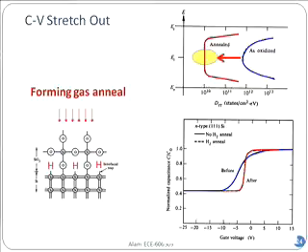And this is a capacitor structure. How do you know? Because in a transistor, you would never have seen that flat region at high frequency. Even at high frequency, it goes back to 1, right? Threshold voltage minus 10 volts here. Do you see that? That's where it becomes flat.